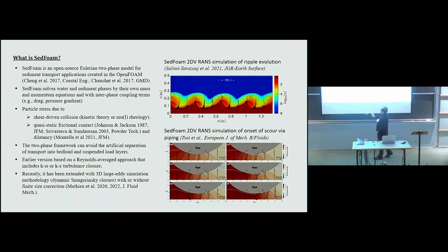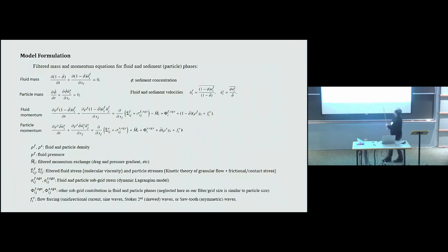The earlier version of SedFoam is based on the Reynolds-averaged approach, but today I'm going to focus on 3D large eddy simulation. So these are the equations we use, the filtered two-phase equations. The important thing I want to point out is that for the closure of the fluid and the particle subgrid stresses, we use a dynamic procedure.